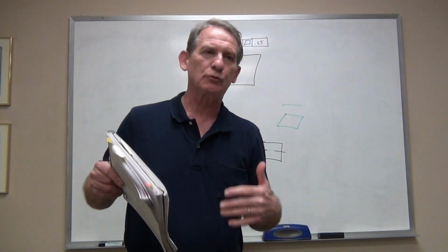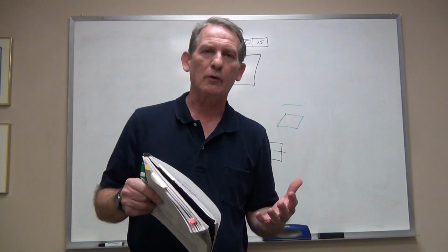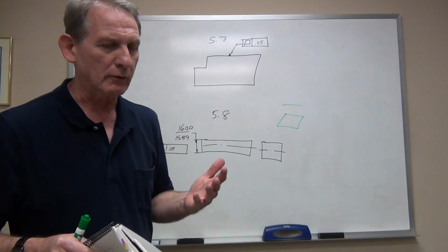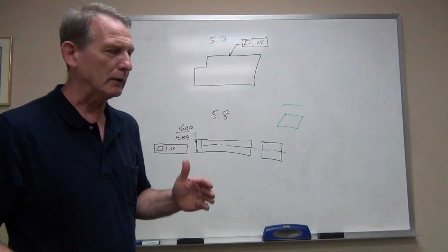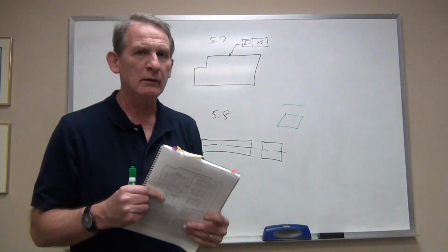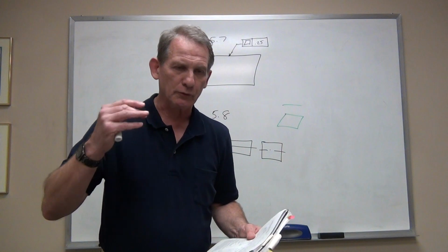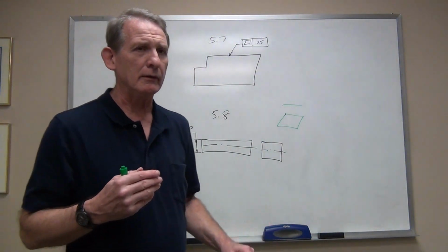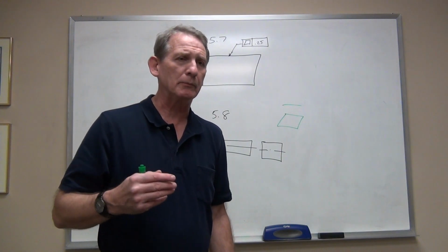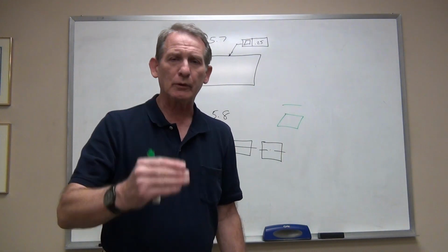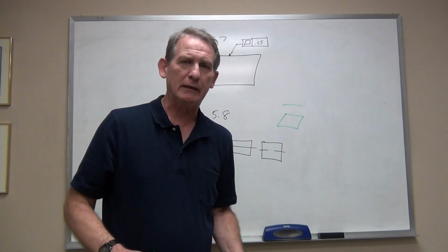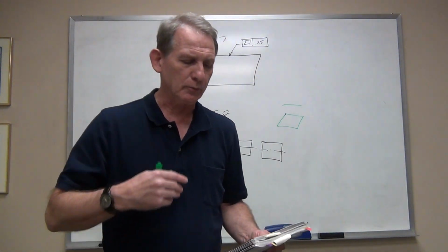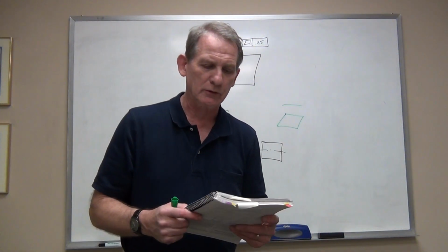We don't control an entire form with a form control in that way. We deal strictly with one surface at a time. Very often on machine components you need one critical face that has to be particularly flat. So that's where you would see this used.